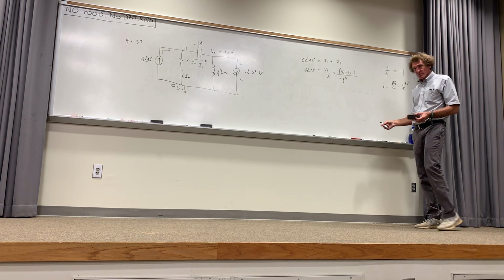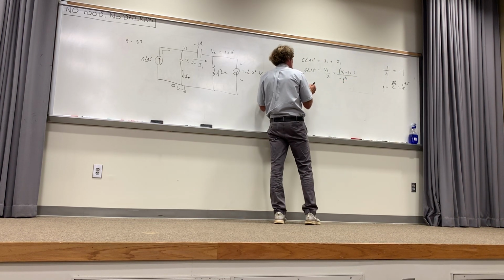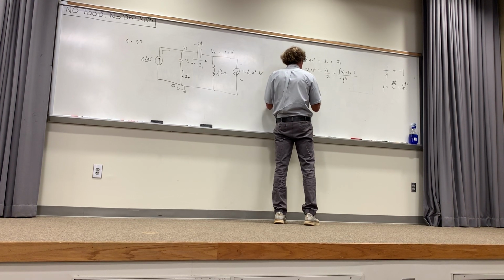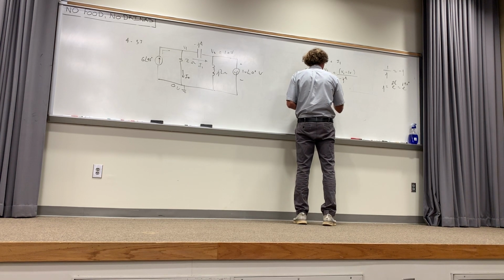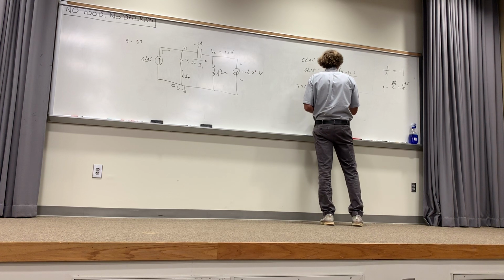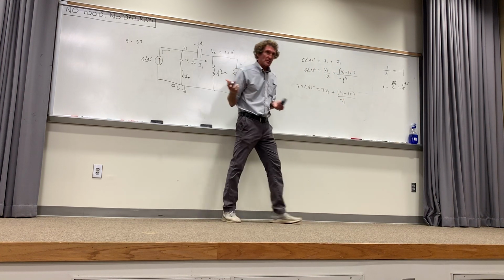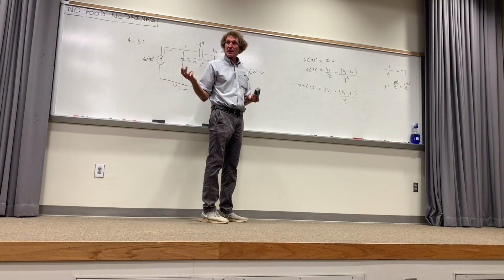So if you want to, and it's up to you, I'm going to multiply everything first by 4, and so I'm going to have 4 times 6, or 24, at an angle of 45 degrees, is equal to 2V1, because I'm multiplying first by 4, and then it's going to be plus V1 minus 10 over minus J. I'm just showing you one of the possibilities. Does everybody see what I've done there? Multiply everything by 4, right? Y'all see it in the back, guys?